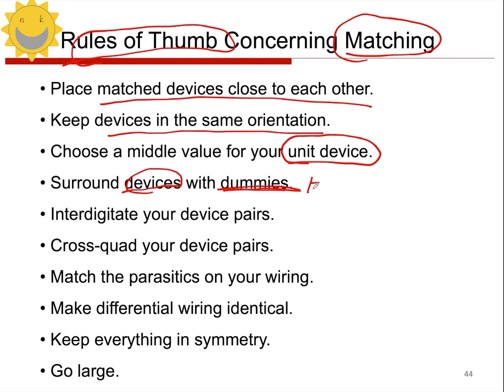Short-circuit treatment, right? We just said that it must be used when matching components. So what happens after the short circuit? You still need to pay attention to its parasitics, right? Although the dummy components are short-circuited, it is possible that they will contribute some parasitics. So you have to consider the parasitics of your dummy.